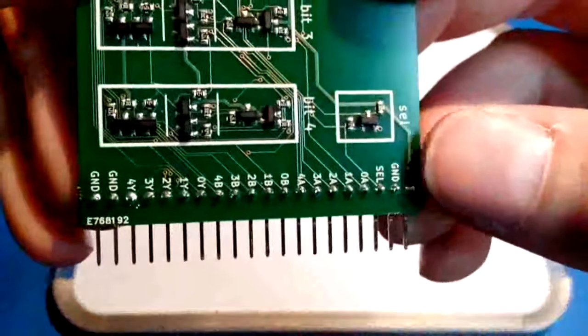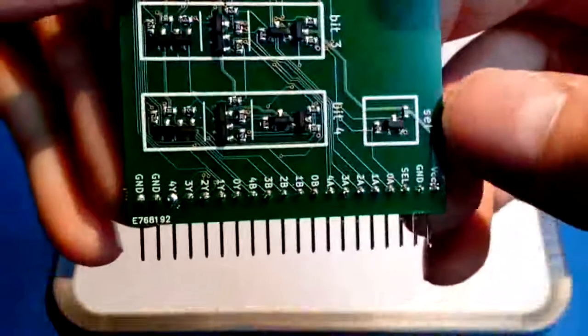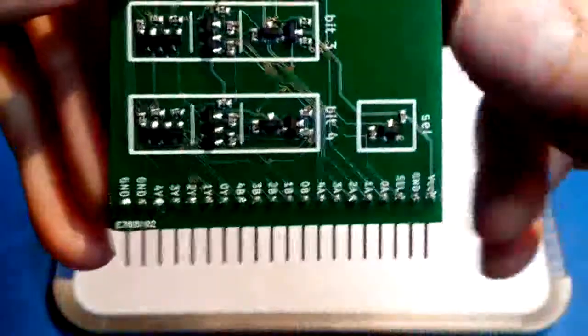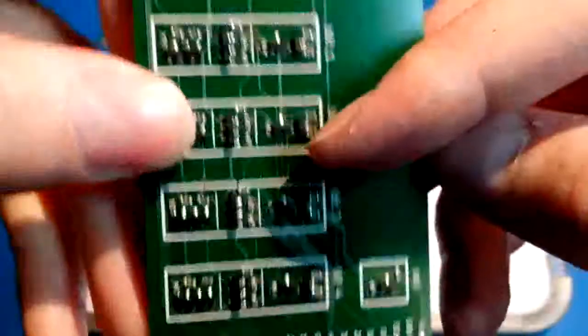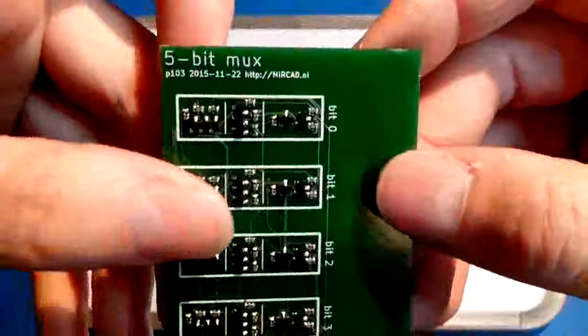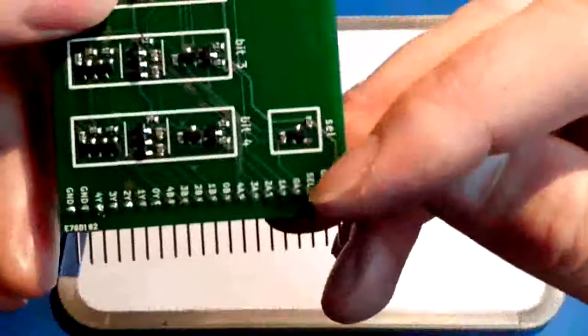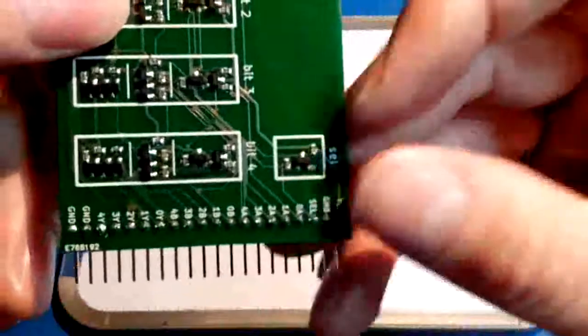If you look at the inputs, there's VCC and ground obviously. There's one select input. So the select input that you just saw on the whiteboard is shared among all the bits. In other words, this board basically implements 5 switches, and all the switches change position from up to down and vice versa when this single select changes.